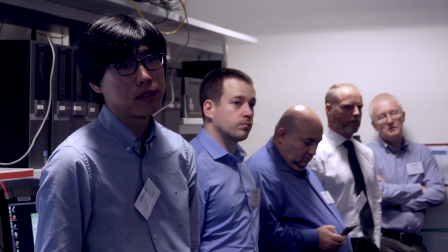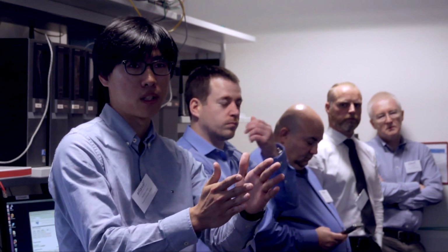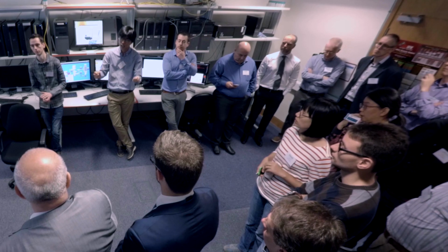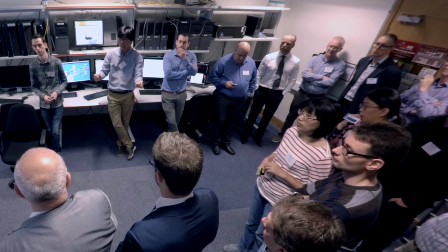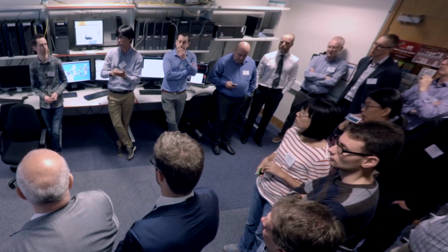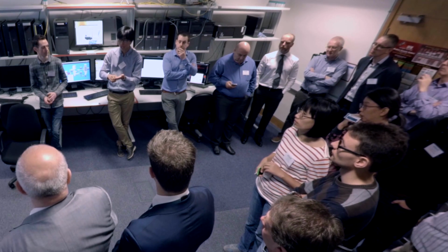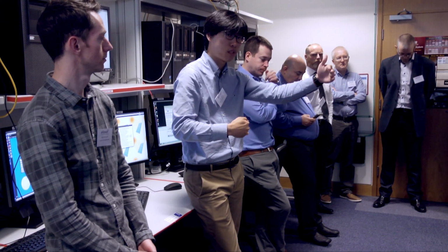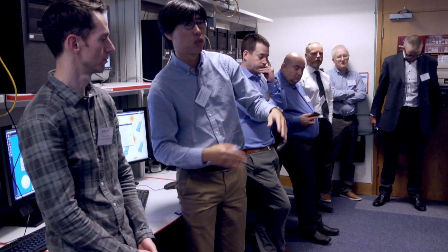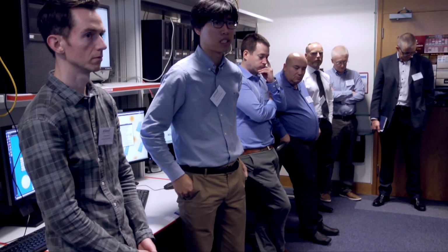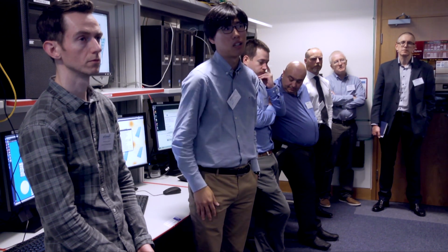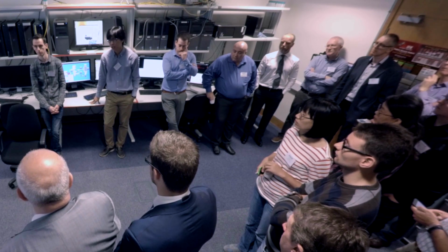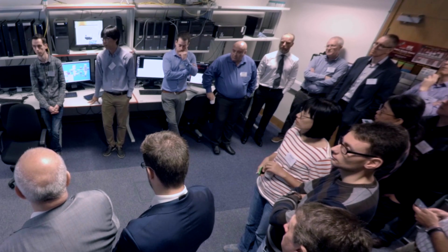The problem is that while you're deriving the rules... Yeah, so I believe we try to reduce the gap between the security experts for the IDS and the system designers. That is why we focus on IEC 61850. IEC 61850 has the capability of providing a description for the system to implement their own system. From that system description, we can derive those rules, run them on the IDS, and give some orders to the regional control and other control loops. That's another focus of this project.